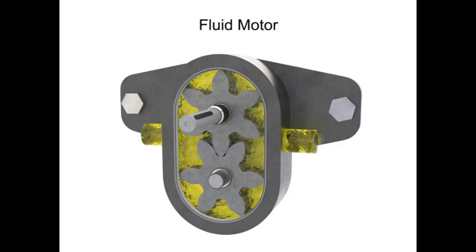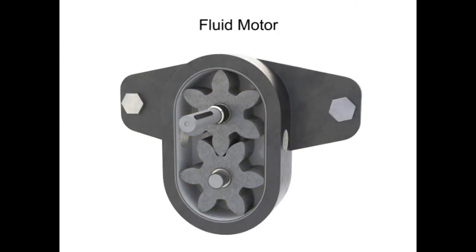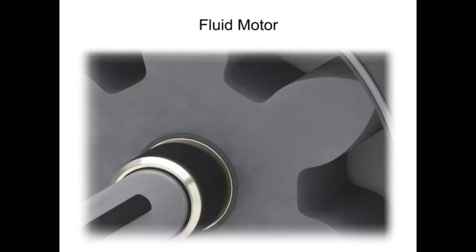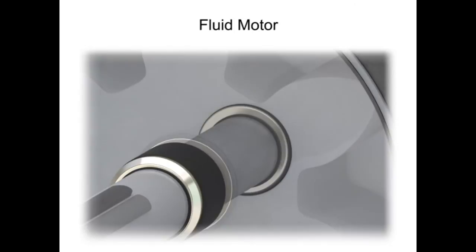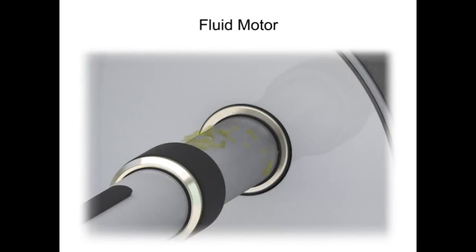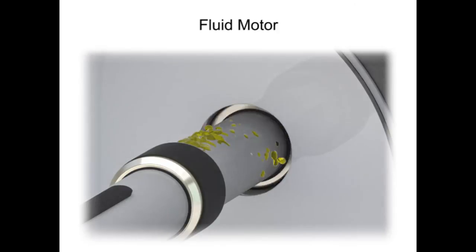In all hydraulic devices, a small part of the high-pressure oil will slip through clearances between the gear sides and the housing and will collect in the seal and bearing pockets. If not vented, these pockets would soon be exposed to the same high fluid pressure as the ports, which can then dislodge the shaft seal. To prevent this from happening, several motor construction methods are used.